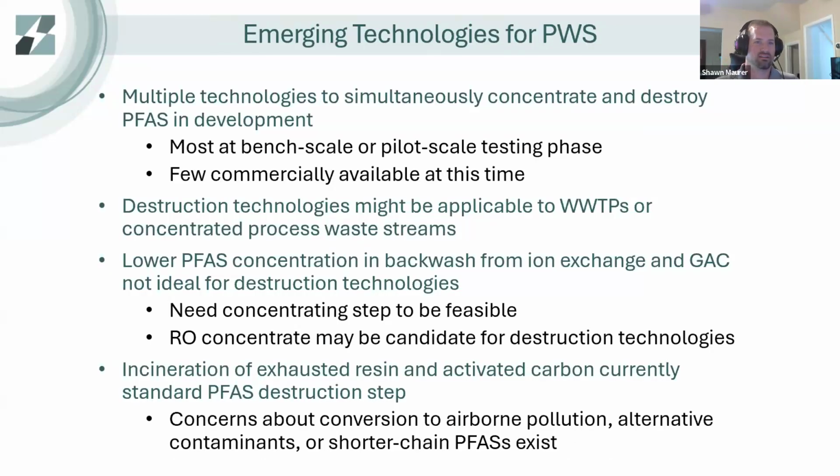Some of the emerging technologies for public water systems. There are multiple technologies available that simultaneously concentrate and then destroy PFAS. Most of these technologies are at bench scale or pilot scale testing phase. There are some that are commercially available but handle limited flow rates. We'll talk about those on the next slide here. But there are very few that are commercially available that actually destroy PFAS in place as part of the treatment process.